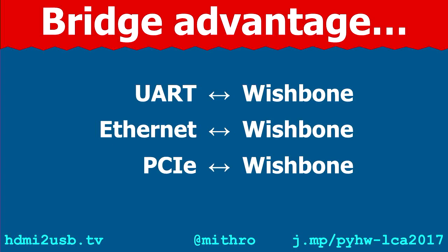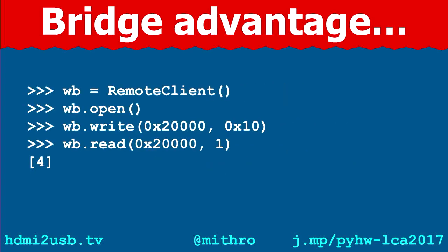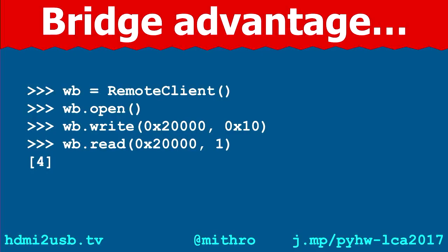And this bridge has another advantage. This bridge then allows you to write Python code on your computer to write directly into the memory subsystem in your FPGA. And so this is what it looks like. On your computer, you're running Python. You can open a connection to it, and this is writing to that memory location, and then you read it back. And I think I got my example wrong, but it looks like that.